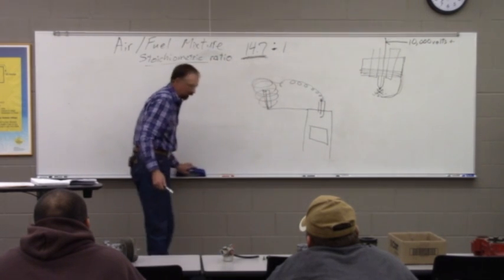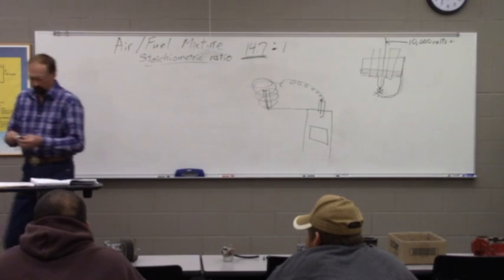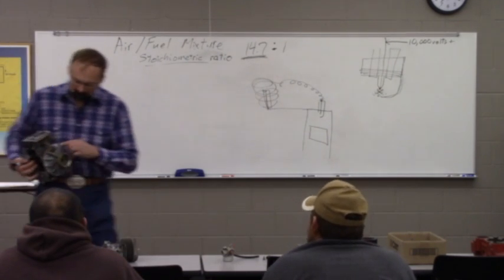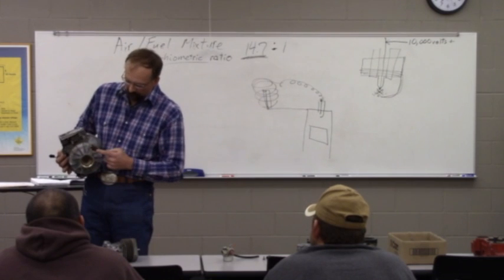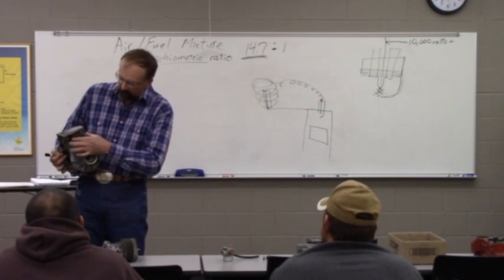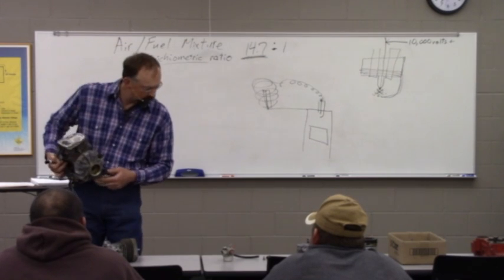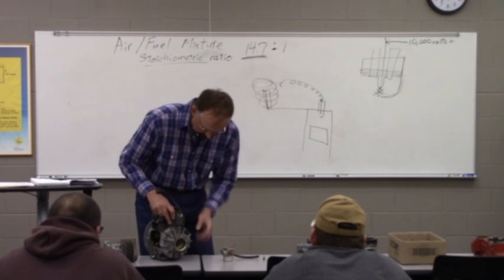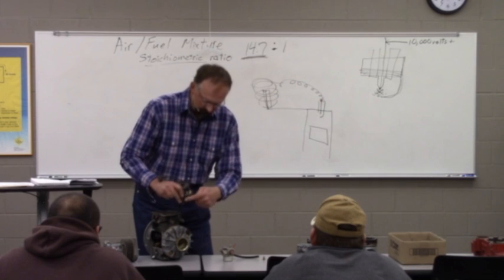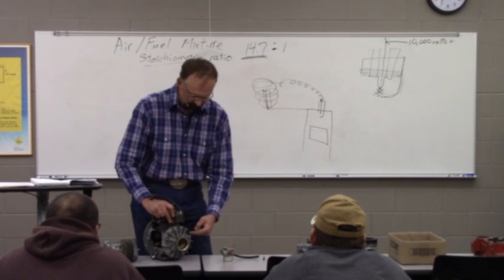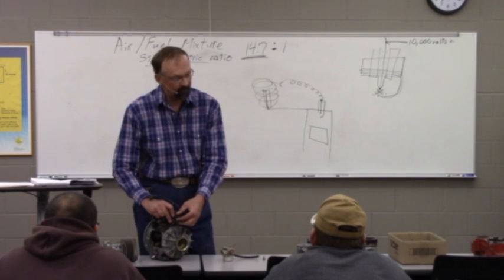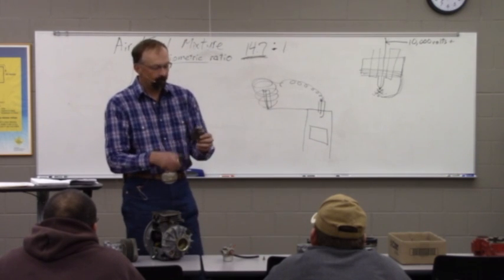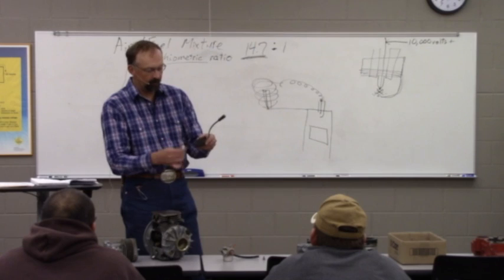So actually this engine here's not a bad example of that. On the flywheel here, which turns, we've got a permanent magnet. And mounted on these two was actually the coil, which I think might be the one from this engine. Sure enough, look at there. So when we pass that magnet past this coil, the magnetic field going into that space and then exiting that space creates an electrical surge in the winding that's in this coil.